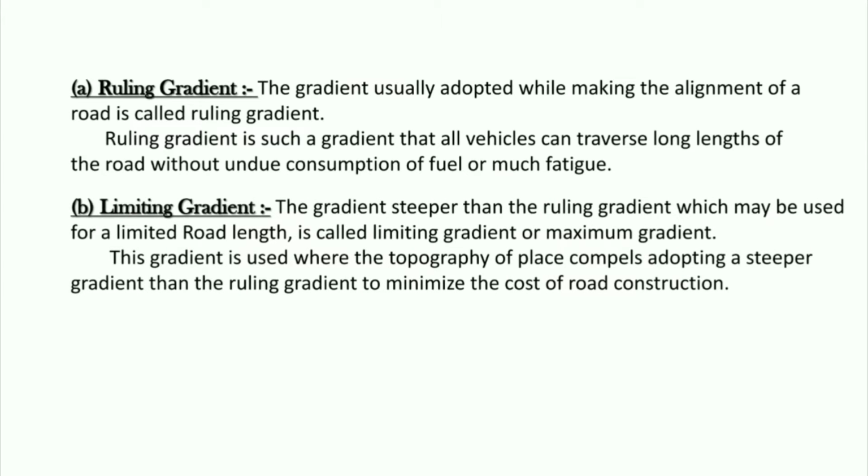Next is limiting gradient. The gradient steeper than the ruling gradient, which may be used for limited road lengths, is called limiting gradient or maximum gradient. The gradient is used where the topography of the place compels adopting a steeper gradient than the ruling gradient to minimize the cost of the road construction.